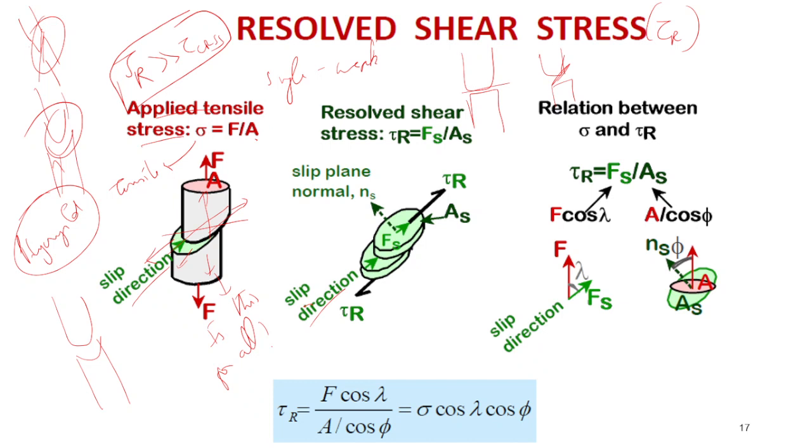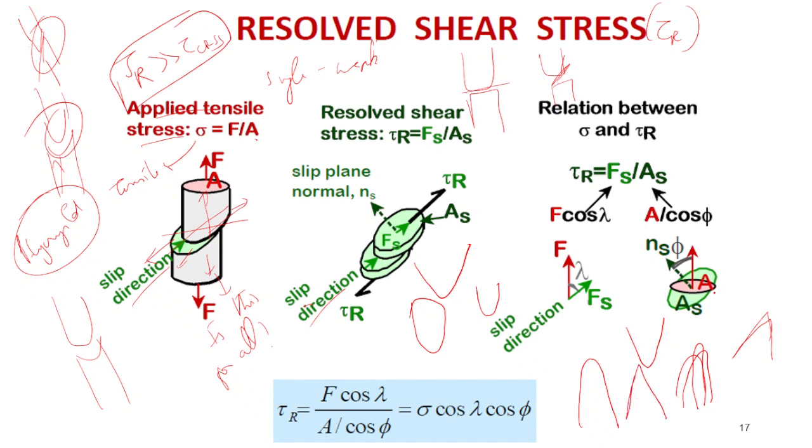Sir, would it be a cone or elliptical? Elliptical means it will be more rounded, you'll have a rounded edge. Usually it will be a cone only, because elliptical means rounded on all sides. Cone means you'll have that perfect taper. In elliptical, there will be very minor taper. In a cone, you'll have a larger taper. As far as I know, it's a cup and cone only. There will be a cup, and then a cone formation. As far as I know, an ellipse doesn't usually happen.